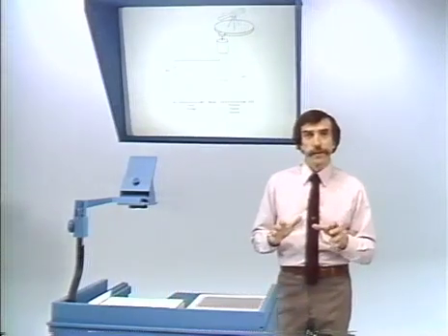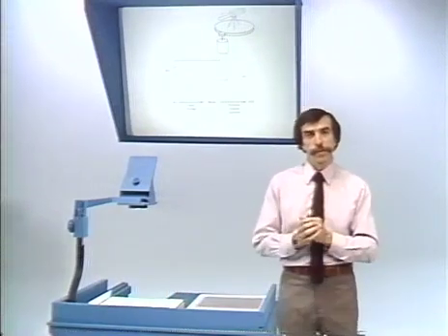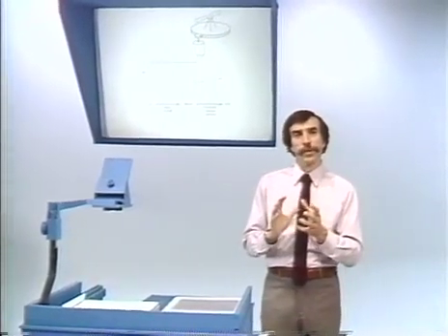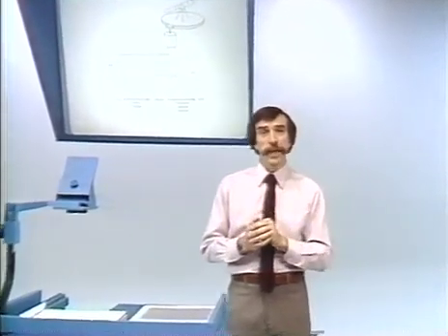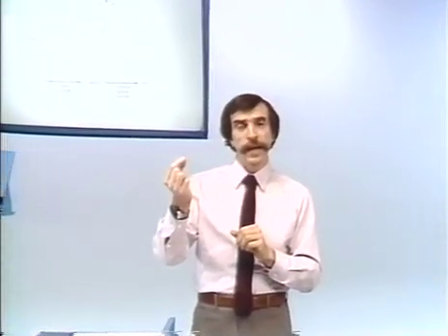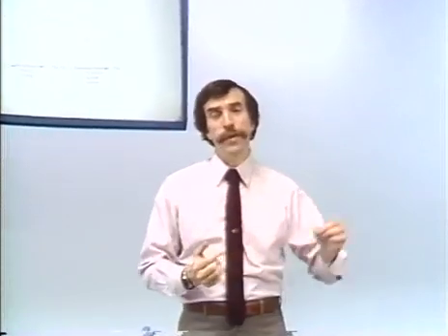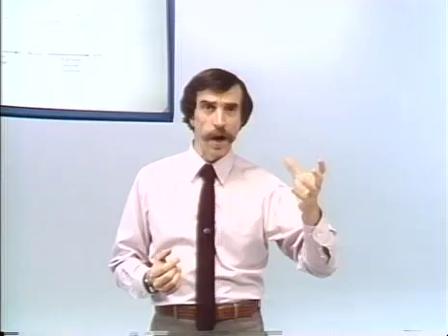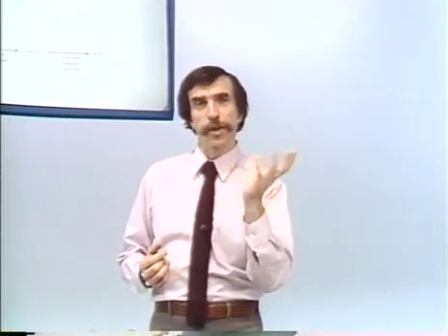However, again, there are enough unknowns in a problem like that so that one is motivated to employ feedback, namely to make a measurement of the output angle and use that in a feedback loop to influence the drive for the motor so that the telescope platform is positioned appropriately.